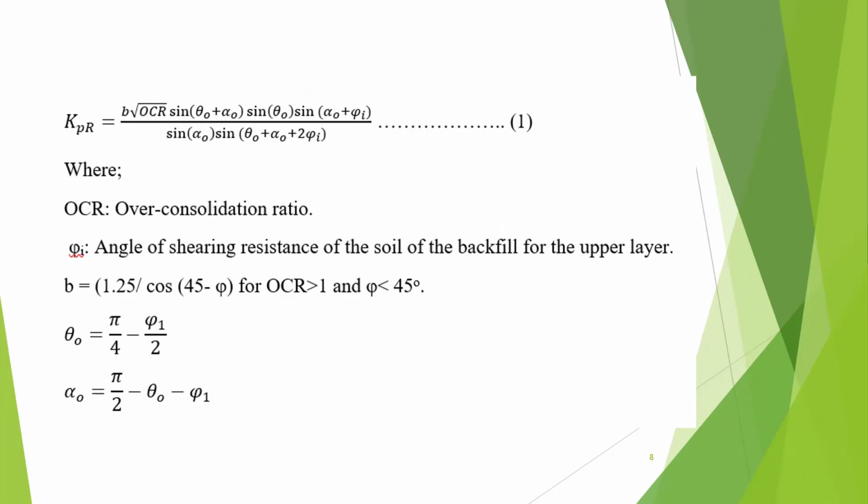Understanding the failure mechanism is crucial. We observe two distinct behaviors based on layer strength. In the first case, where you have a strong layer over a weak one, the failure plane is deep. It cuts through the weak bottom layer before moving up. However, in the second case, weak soil on top of very strong soil, the failure is shallow. It stays trapped in the top layer. Our theoretical model distinguishes between these two physical realities.